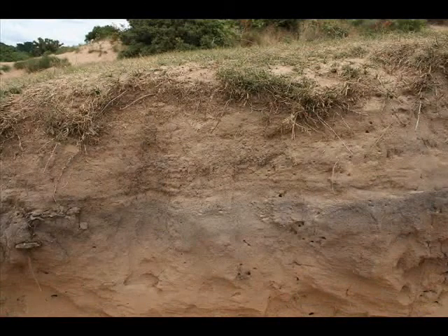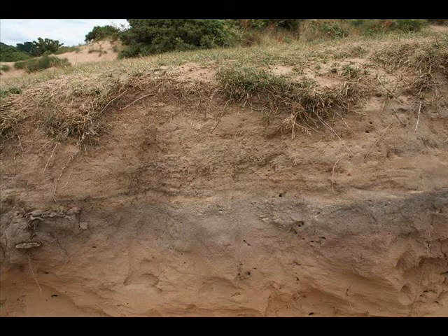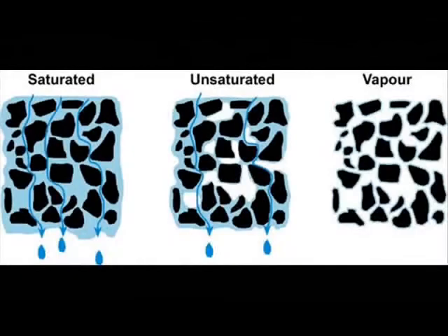The soils for both areas, and what will be found throughout most of Stevens Point, is Plainfield loamy sand on 0 to 2 degree slopes. This is a good soil for rain garden construction because they are excessively well-drained soils, allowing water to move quickly through them.